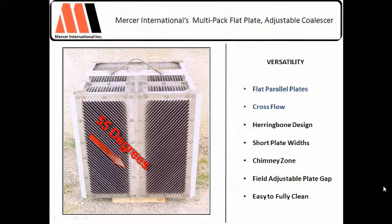And the flat plate design at a 55-degree steep angle, that's where we are here. If you're in a 55 or 60-degree angle, you have a much better shot of solids falling down and out of the plate pack system. And if we're steep and we have a flat plate design, there are no nooks and crannies. If you look at the other designs we looked at today, lots of nooks and crannies, lots of places for the solids to lodge.